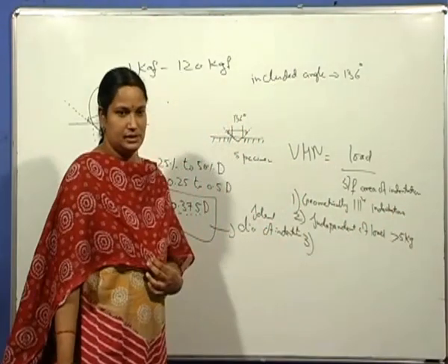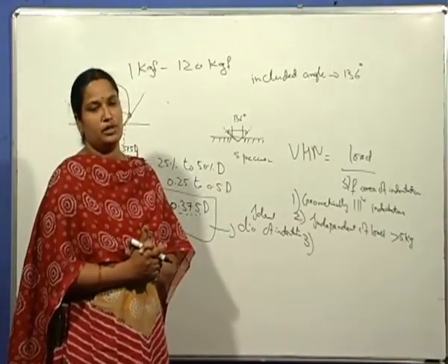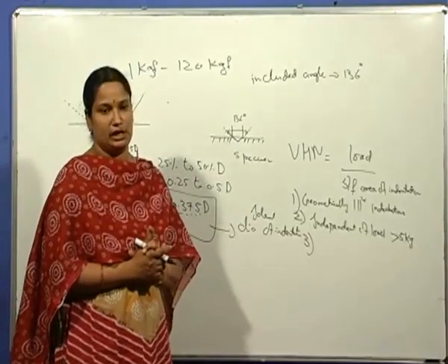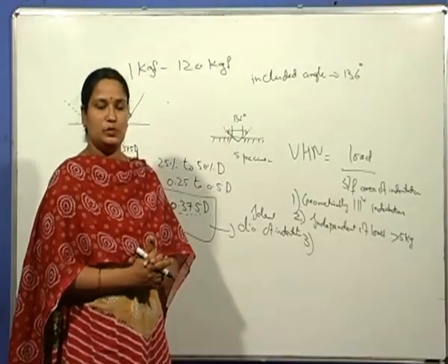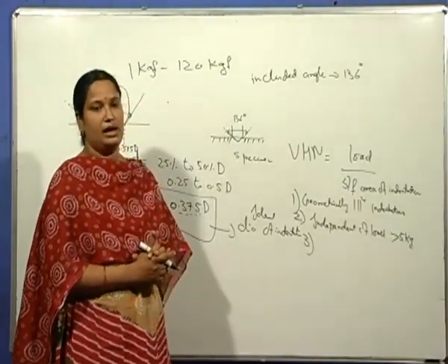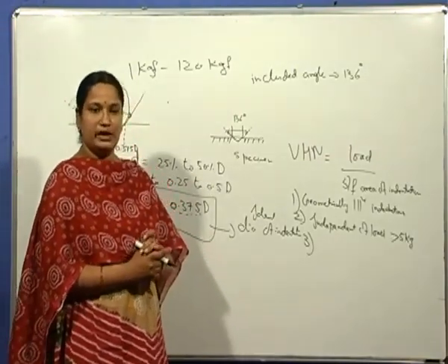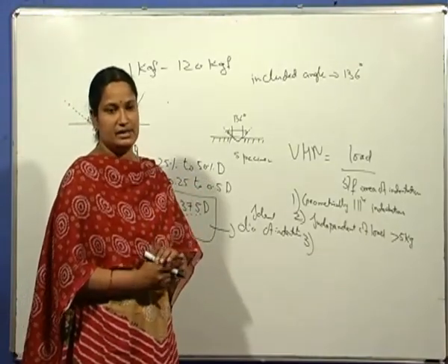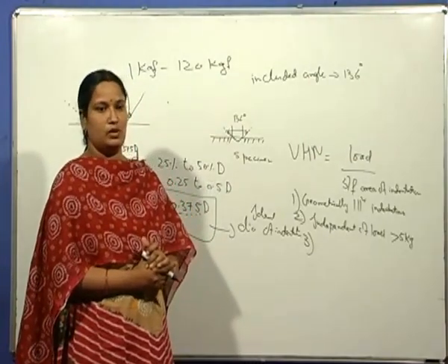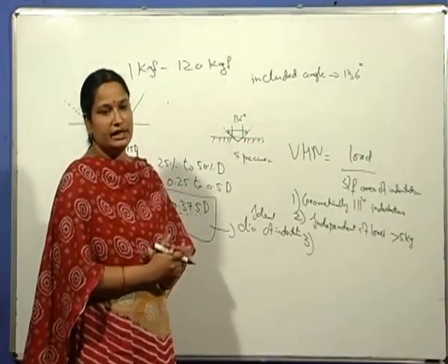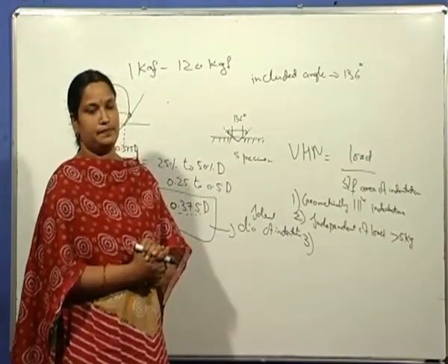Third advantage is, Vickers hardness test can be used to find out the hardness of various metals and alloys, ranging from the softest material to the hardest material, as well as it is also used to find the hardness of coatings given on the surface of the materials, to find out the thickness of the hardened layers, carburized layers, to find out the coatings on thin sheets also. There is no need to change the indenter or the load for the case of Vickers hardness.